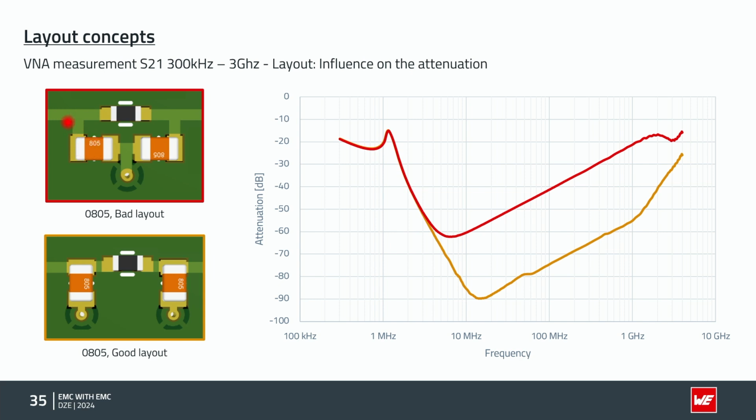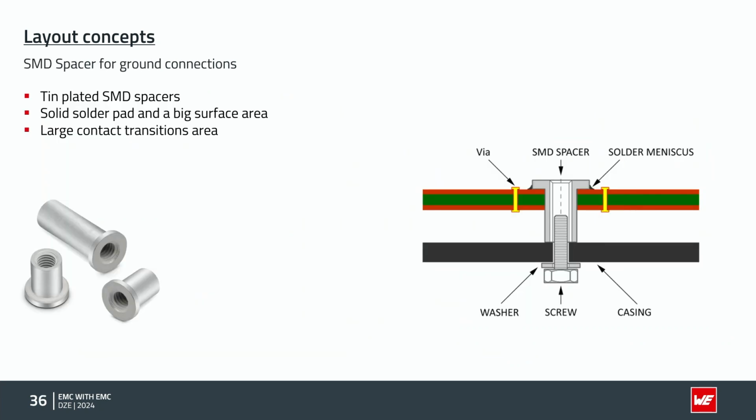This is an inductance. One via is an inductance. So some parts of the noise are going to go this way, and some parts will say, no, that's way too high for me, I will go the straight way to whatever that's going to be. And that's the hard thing to see. Okay, we have an inductance, we have probably some kind of capacitive coupling and some transformer coupling, some magnetic coupling. So be aware of that.